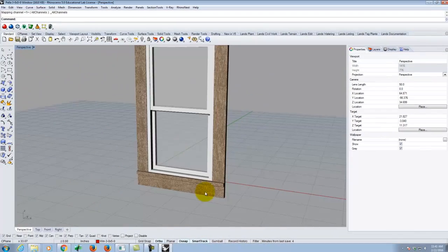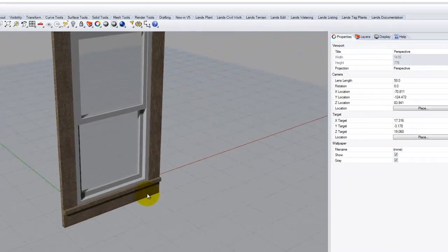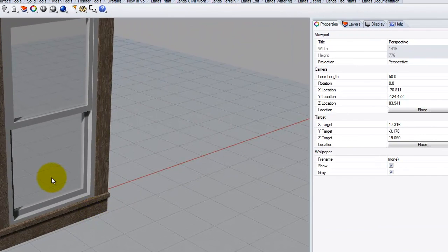And this is actually something I've done in practice, doing design work. Again, more on the traditional side, but when you need to populate a building with windows, if you already have the window made, it's really easy. And if you decide you want to change the trim from 2x4 to 2x6 or vice versa, you change it once on the block file and it populates back through your whole drawing, which is, again, the advantage.